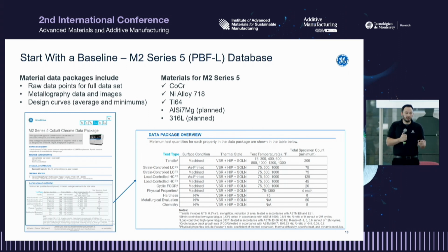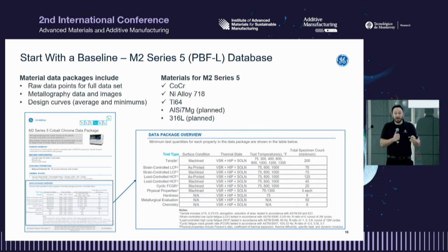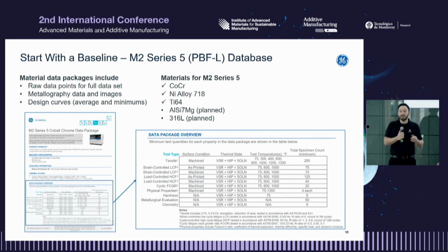We're too young. As you partner with machine OEMs, you should be asking for things like you see on the screen here. Give me all of the data that you have and tell me the pedigree that's behind it. And by pedigree, I mean, can I believe the data that exists? Do you know the powder history? Do I have a heat treat? If I don't understand the first 8 steps, that 9th step of characterizing, pulling a tensile bar, looking at microstructure, there's no reason for me to believe any of that.